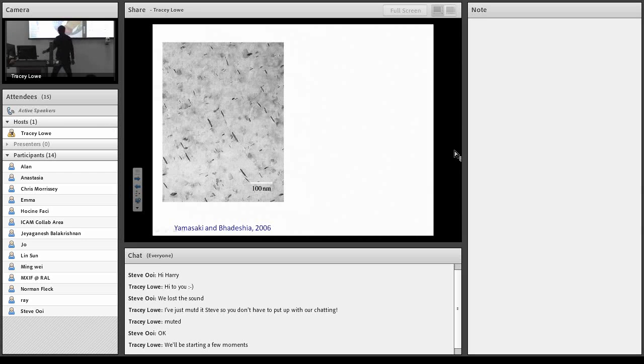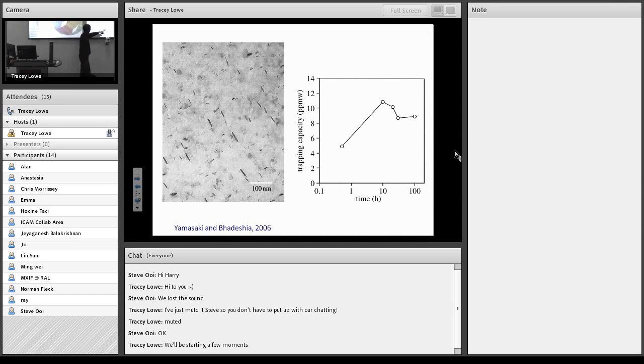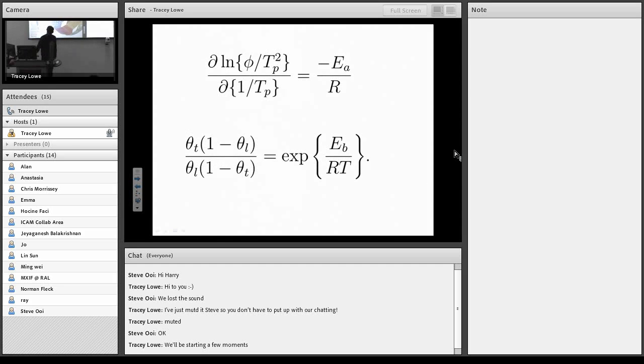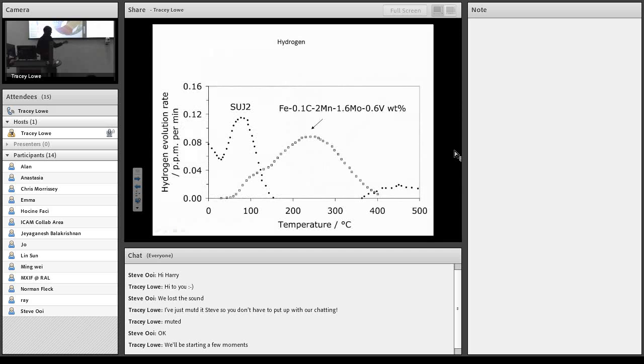Introducing these particles gives you a large trapping capacity, where say 8 parts per million by weight of hydrogen can be absorbed at those carbides, and it more or less removes the static fracture problem from these bolting steels. So this has actually been a commercially available product for many, many years. And we want to do something like this for some of the work that we're doing in this BP-ICAM project. But the theory that goes behind these curves is not well established. And let me tell you why.